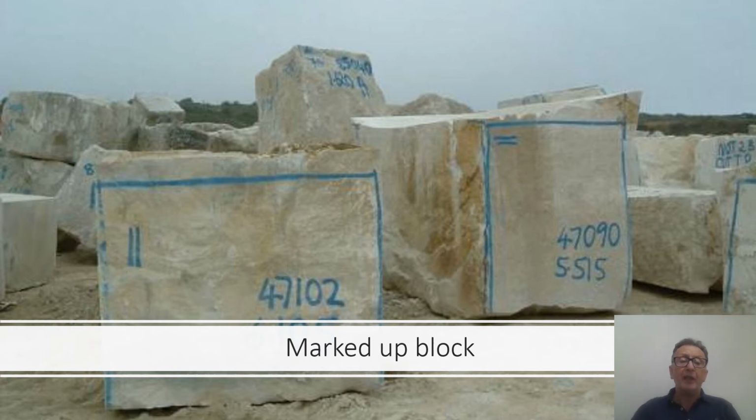If you look closely, the two blue parallel lines marked onto the blocks are also indicative of the direction of bedding of that material. Again, it's important to look at these features to see how consistent they are within a stone when you're at that preliminary selection phase and understanding of how that material will look and likely perform.